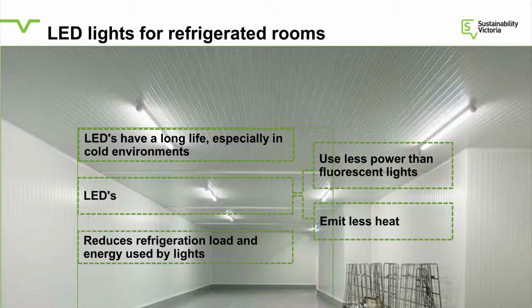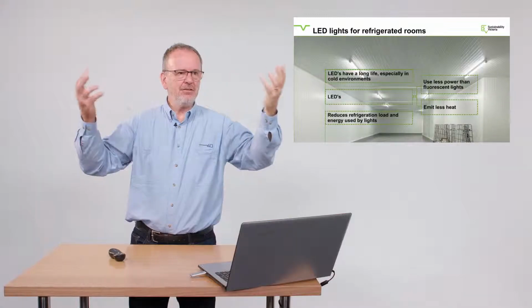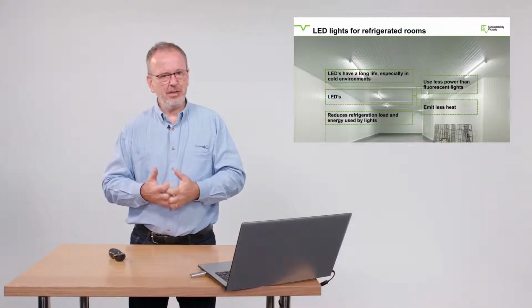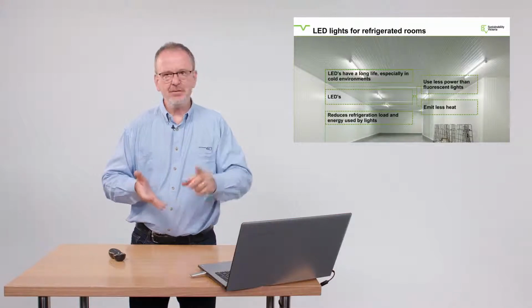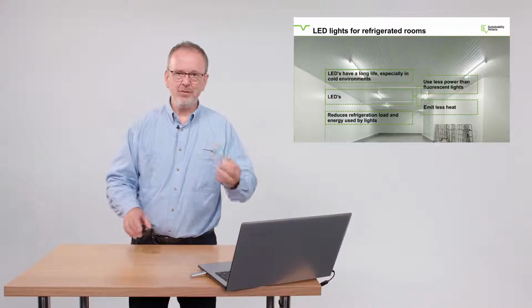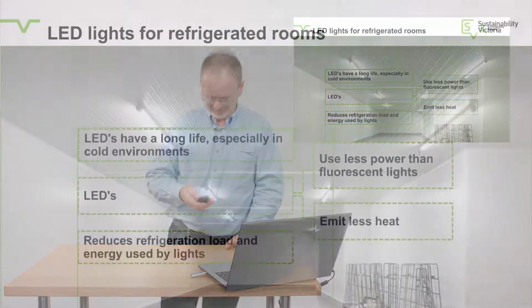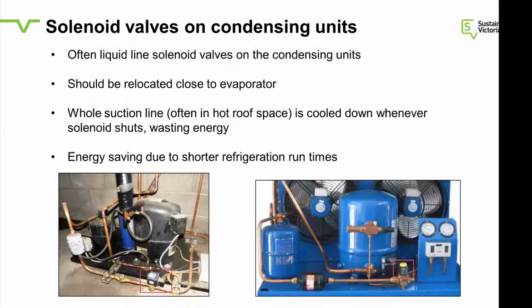And they last longer. How often do I walk into a cool room and there are badly running fluorescent lights, because it's hard to get at and you've got to get on a scissor lift to turn it off, to change them around? With LEDs, you don't have to change them that often. They last much longer. So you get better light, safer maintenance, lower energy use. That's why I think every cool room deserves LED lights. So yeah, there we go.